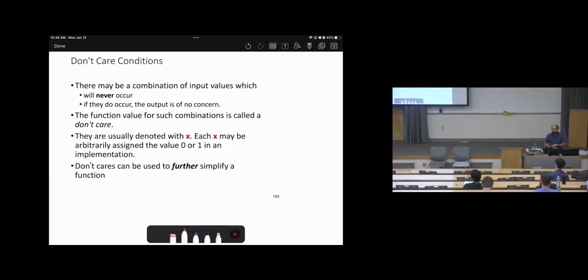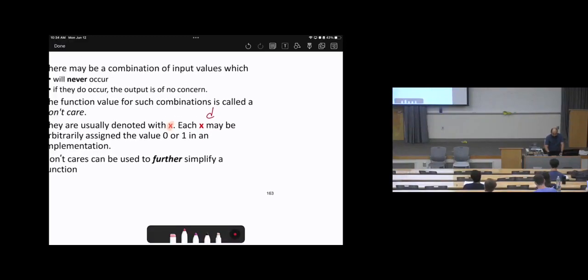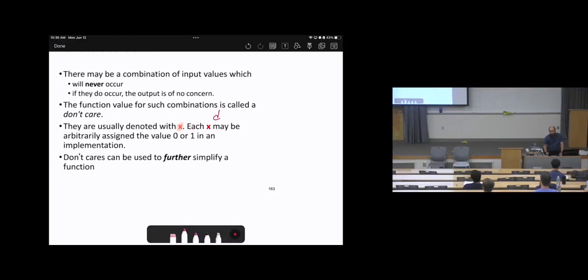So you will see it in the minterms or the maxterms as a don't care function. Sometimes we represent this by X, sometimes by D. The textbook most likely represents the don't care by D. Here in the notes, it will be represented by don't care. So the don't care means we will use it if we need it in Karnaugh maps.